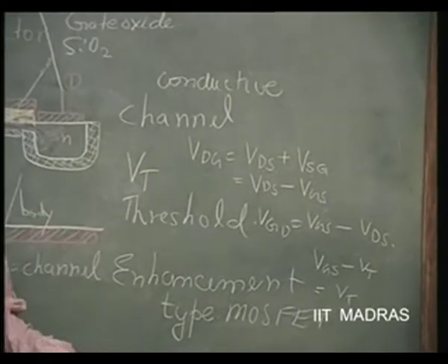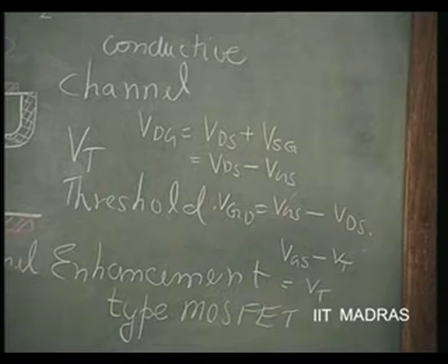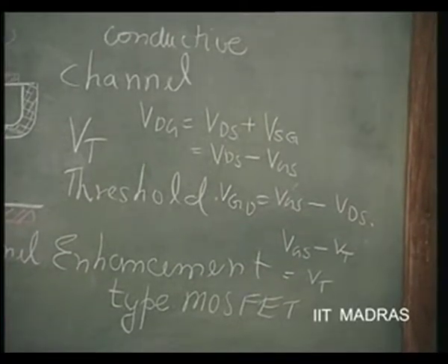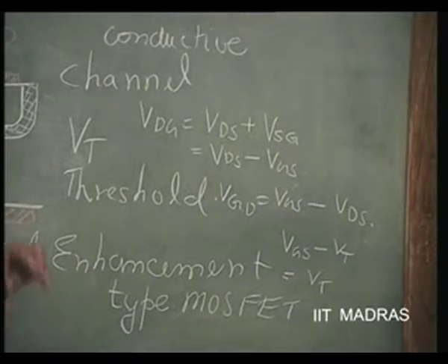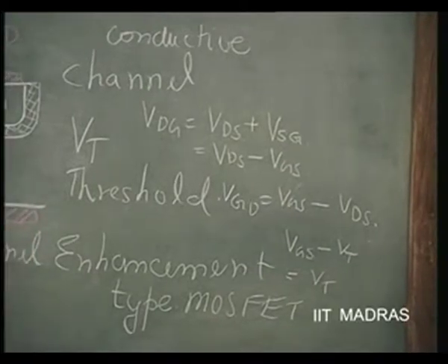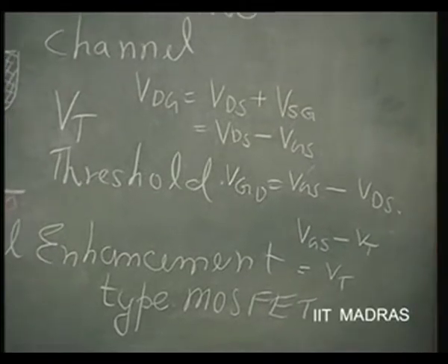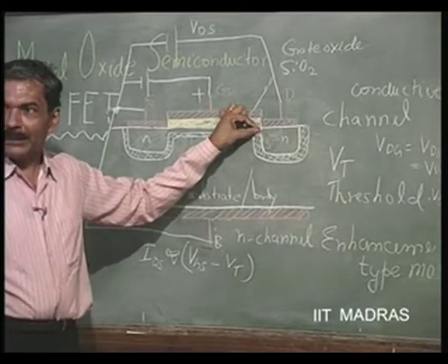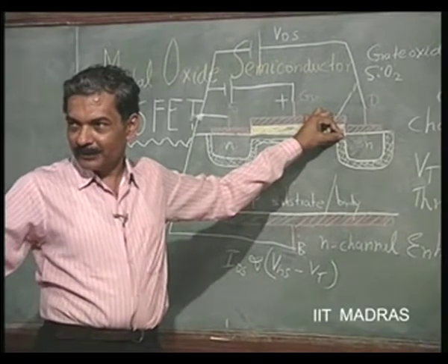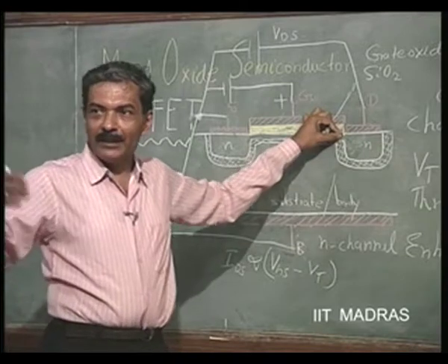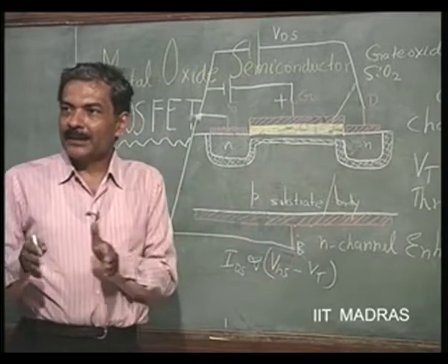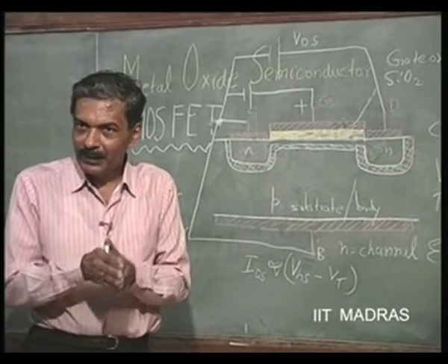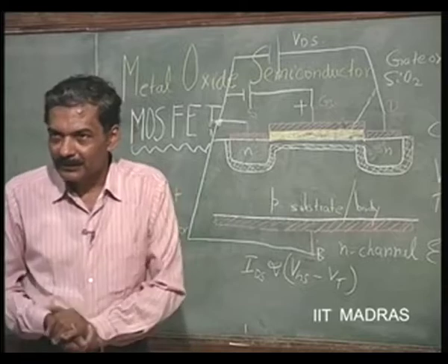So, at that particular point you have only threshold voltage as the voltage applied between drain and gate. That means the entire channel has been blocked to a certain extent, right. Here, when you apply threshold voltage, the channel has just got formed, right. The channel width will be dependent upon the excess voltage over and above VT that you are having between that terminal and gate.